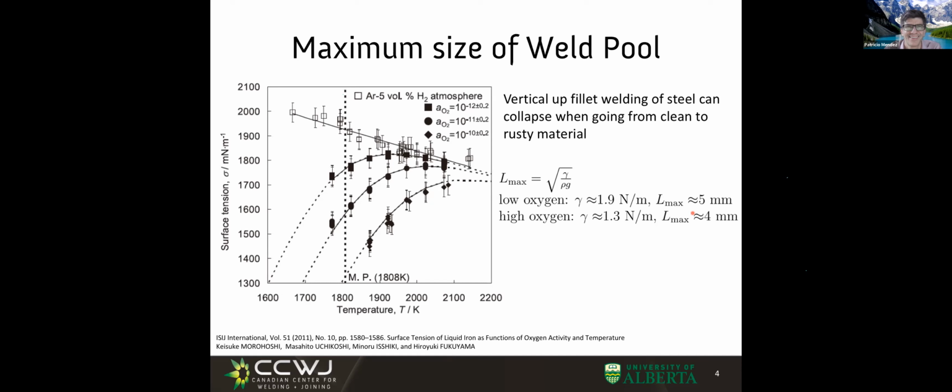Why? Is the oxide having the effect of Teflon on the weld? Isn't this amazing? What happened is that when he started to weld over the rusty spot, all of a sudden, the surface tension, instead of being a surface tension that can hold up the droplet, the weld pool, barely but hold it, became too weak to hold the bead.